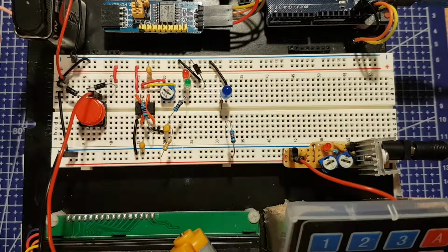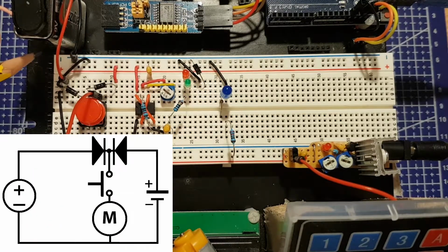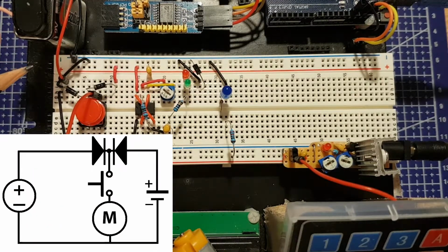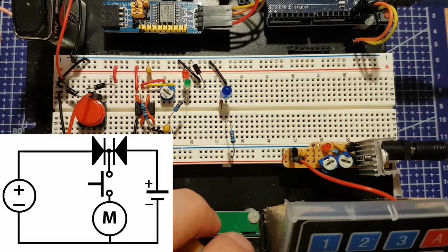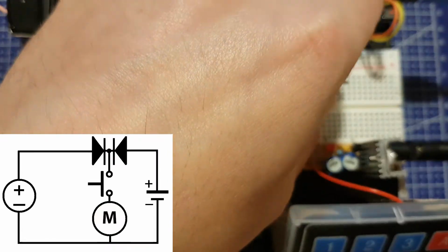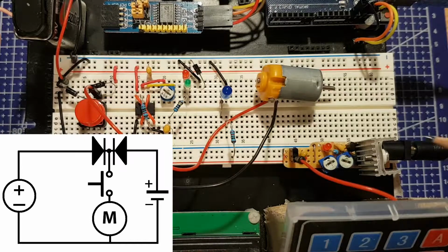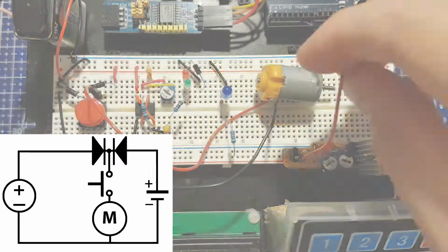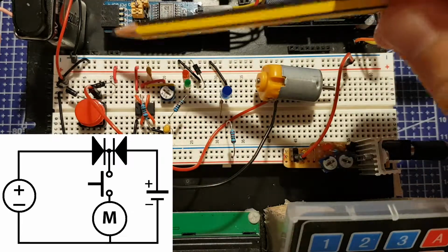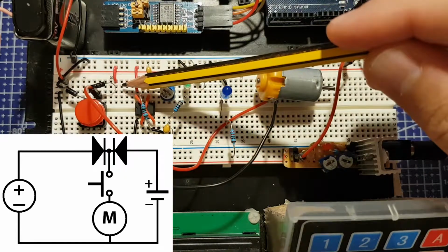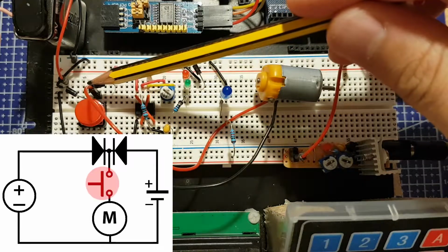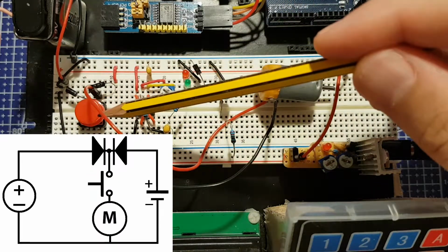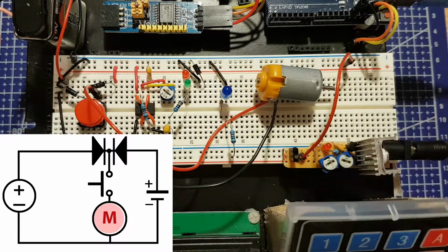On the breadboard we have our battery on this side here. From the battery positive into our first diode here, into a switch, and then into our motor. We have our power supply plugged in here. We have our positive from the supply coming up to the rail here, going into our diode here, into the switch in the same place as the other diode, into the motor and back to ground.